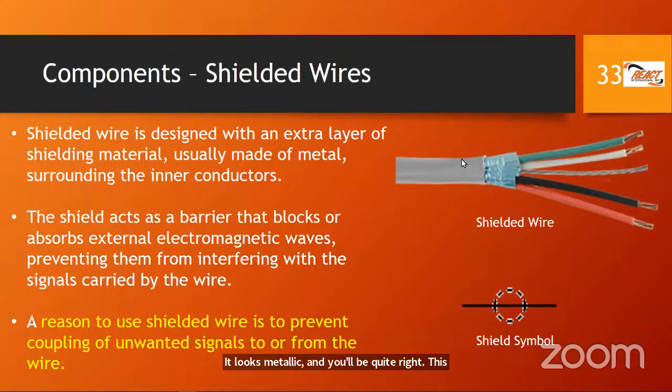So you have the PVC or whatever outer jacket, then you will have some insulation for the individual wires so they don't touch each other. But then you have this curious bit of foil here, aluminum foil perhaps. That is shielding. So this becomes a shielded wire. And we do that to prevent interference from impacting our cables or wire, or this wire from interfering with signals on another wire. So that's the concept of shielding.